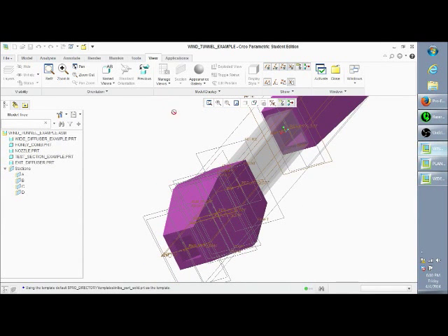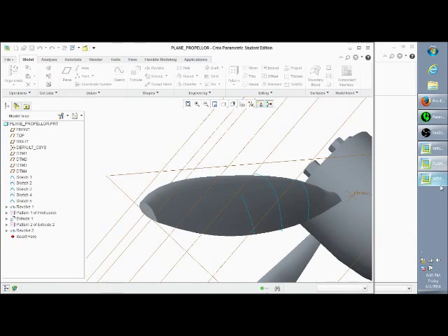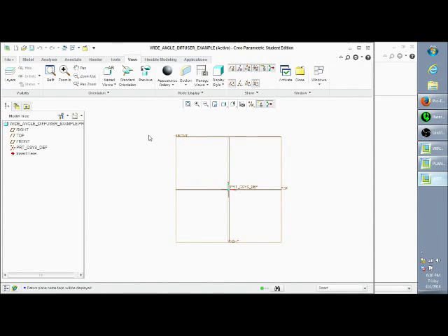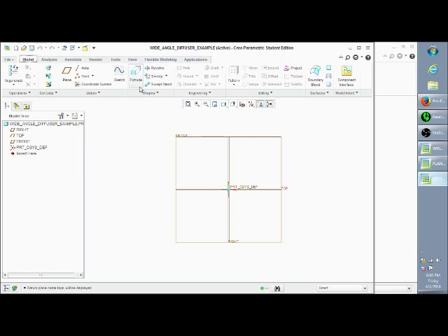Just so you guys know, and I'll show you what exactly will happen, you can't have more than one closed loop within each protrusion. If you've experimented with the extrude tool before, you can see that you can create that box, that frame, within the extrude tool and extrude it out. You cannot do that with the blend tool. So let's just open up the blend tool. Sorry, kind of sidetracked in there.